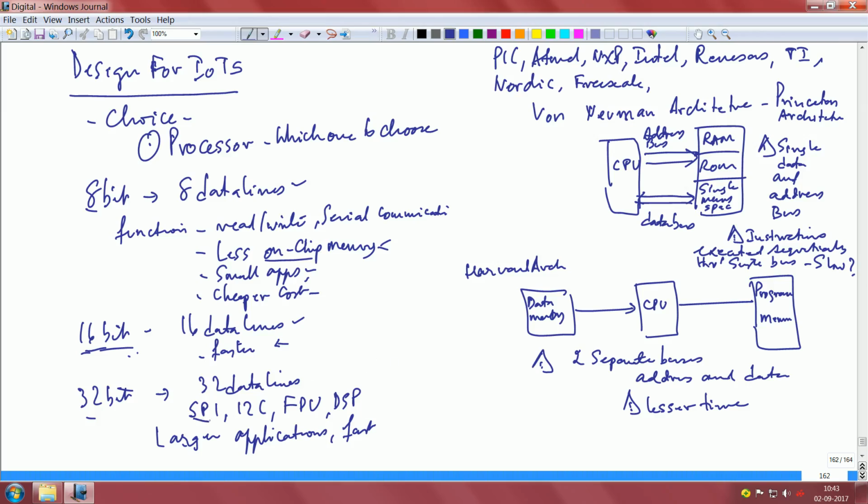Well, I can point you back to what I wrote here. You can have support for digital buses like SPI, multiple of them. You can have I2C and SPI, both digital buses for different sensors which are available. You can have 16-bit and 24-bit ADCs which can be supported.